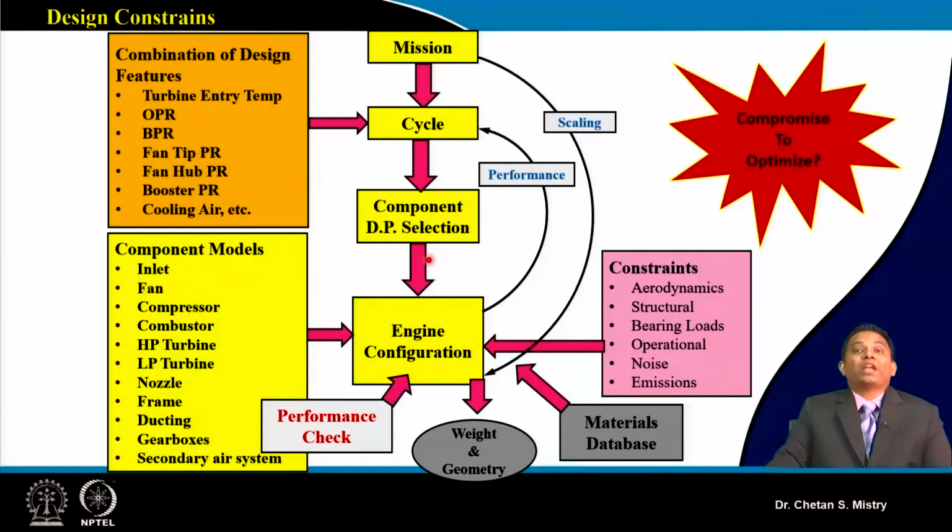When we apply those aerofoils, we need to iterate with our design procedure. We need to check pressure rise, efficiency, operating range, and stall margin. All those things need to be checked. Those checks are done at test rig level, and later tested with the actual engine.